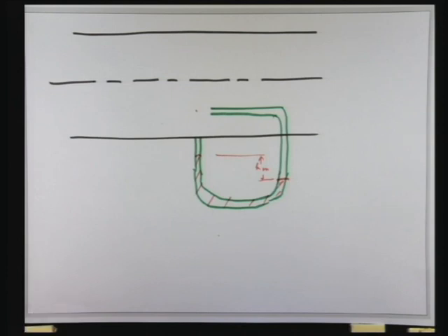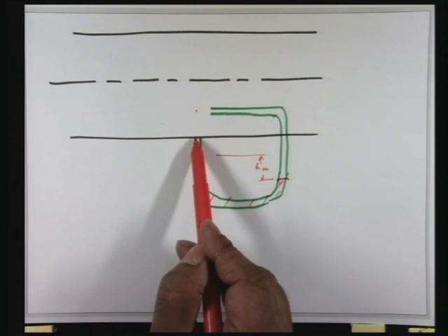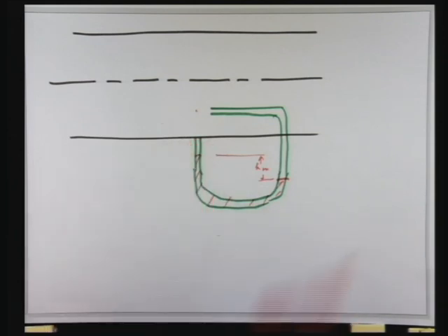This is not a stagnation point. Although the velocity is 0, it is not a stagnation point. The concept of stagnation point is coming from inviscid flow. Because I have read in some book, they are telling there is no velocity along the tube axis while the fluid enters into the left limb.